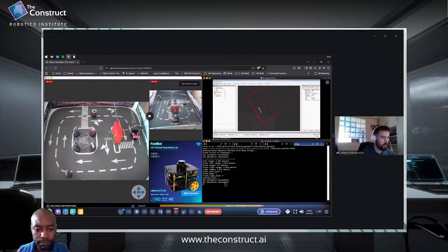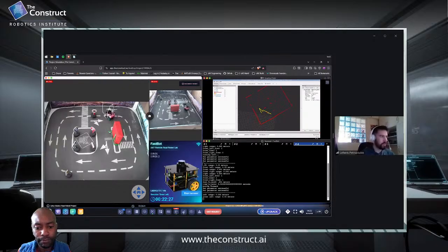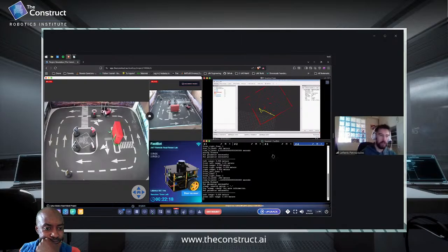First, it takes some measurements from the sensors that the robot has: from the front of the robot, the front left, the front right, and the left and right sensors. So we can measure the distance that the sensors see and decide which way to move, whether to go straight forward, turn left, turn right, or anything else.